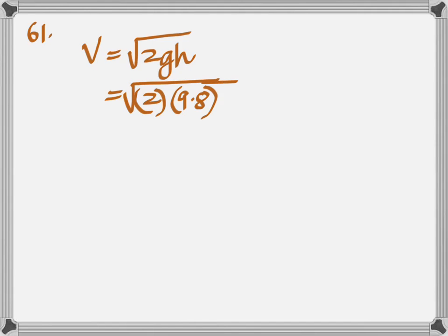I did this because when I was teaching I did not touch on that. This is another application of Bernoulli's principle. It's called Torricelli's theorem or Torricelli. How do you say it? Torricelli? I knew Italians. Okay. So that's it. Can't you use that directly to get the answer here? How? Like this. 2GH. Which is what he was trying to say, kinetic energy is equal to potential, but you know, you have to go there actually. So, all right, 61. 62.